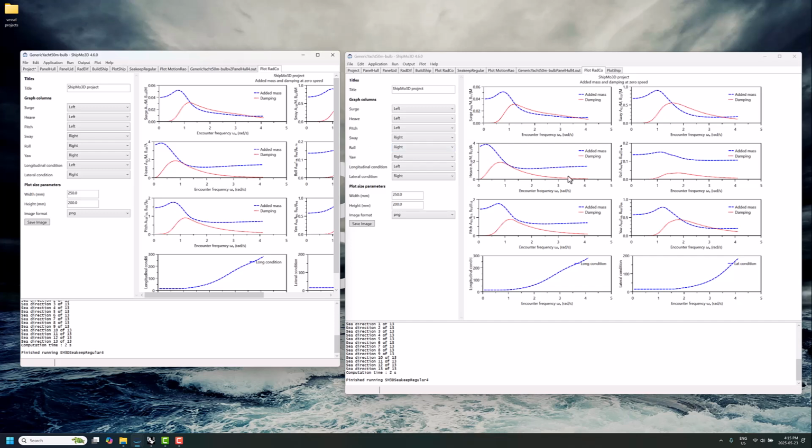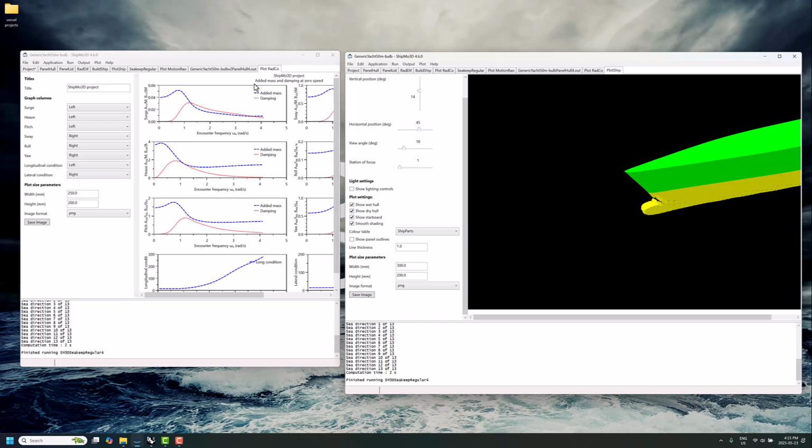I think it's one of those things that's an aggregate. It depends on how the face is oriented, which degree of freedom it might affect, and that sort of thing. But mainly, I think this emphasizes it's good to have a workflow where you look at the mesh visually, do a visual check, and make sure things are looking good at various stages in the analysis process. And of course, it's not hard to fix. It does mean you're going to have to redo the radiation diffraction calculations. And generally, intuitively, you'd expect that the bigger the hole, the bigger the impact it's going to have.